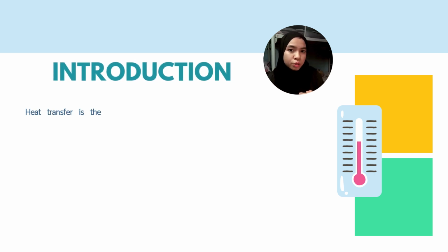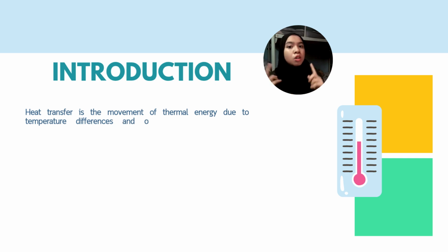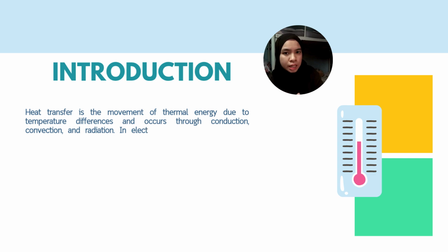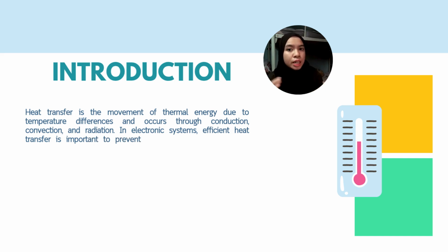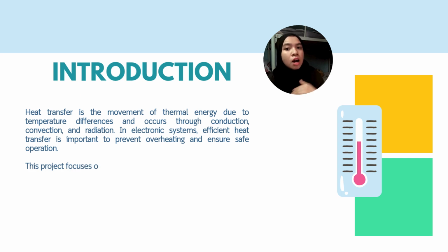Next, moving on to the introduction. As we know, thermal energy moves due to temperature differences via conduction, convection, and radiation. In electronic systems, efficient heat transfer is critical to prevent overheating and ensure safe, reliable operation. To address this, our project focuses on passive cooling using heat sinks or fins. By geometrically increasing the surface area, these fins significantly boost heat dissipation through natural convection, completely eliminating the need for